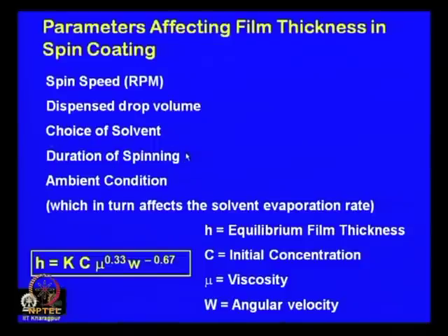Well, duration of spinning is partially important because if you are not well aware of the spin coating technique, and let us say you choose to spin your substrate for 10 seconds, then that might be critical, because that time window of 10 seconds might be too short for the major part of the solvent to evaporate. This can be dangerous if the rotation stops. The centripetal force that you were applying for enhancing the spreading of the liquid layer on the substrate is turned off.